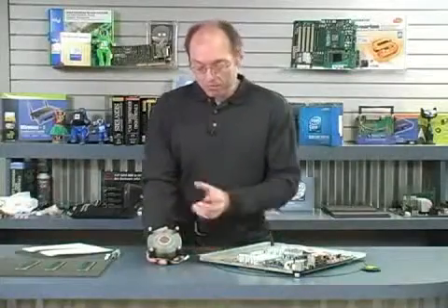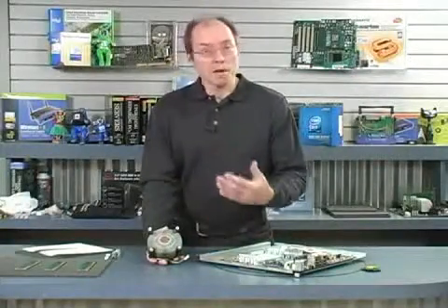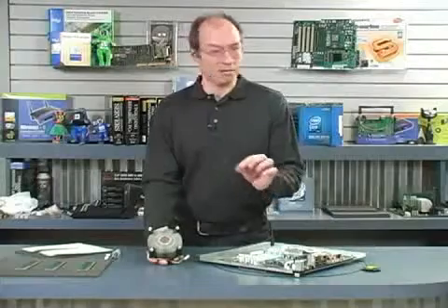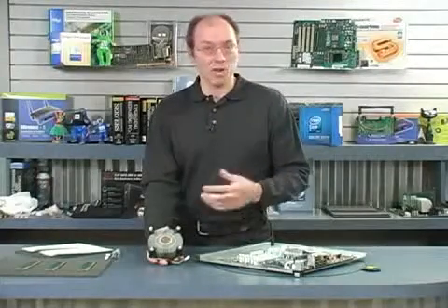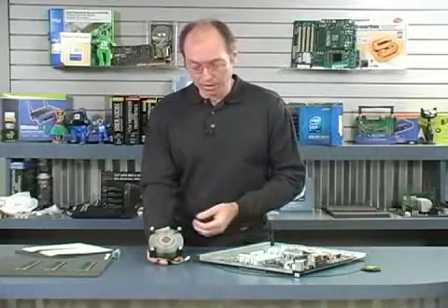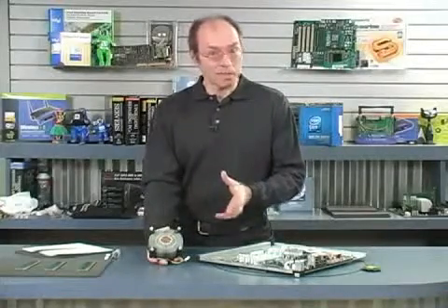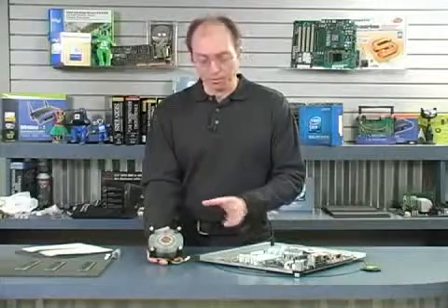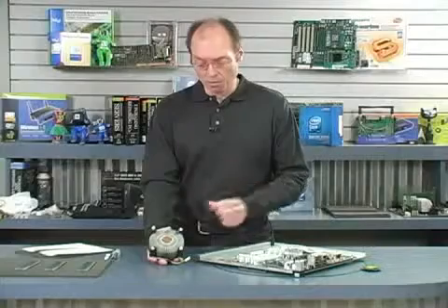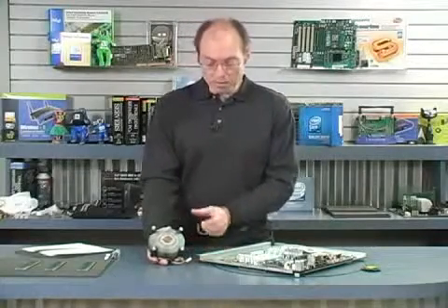Now, why the different materials? Well, copper is one of the best thermal conducting metals that there is. Silver is a little bit better than copper. It's like 5% better as a thermal conductor, but it costs 80 times more, so we don't usually see solid silver heat sinks. However, a solid copper heat sink would really be the best design. It would conduct the second most heat next to silver away from the processor.